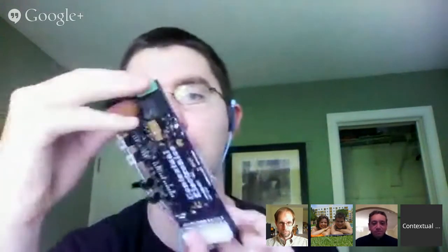That U5, or U3 rather, the temperature sensor. That'll be another one, but really until we get the ADC in there and up and running, it's kind of a moot point. That one is sort of fun though because you can connect it up pretty simply and read the voltage out of it, and then go look that up in the table and say, oh yeah, that matches what I would expect.